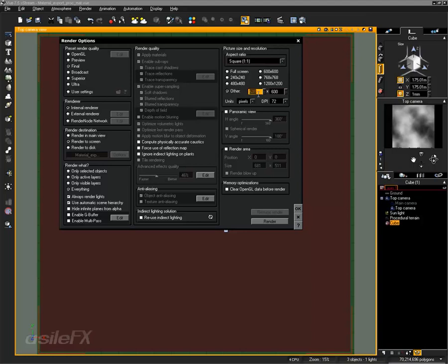So using a very high resolution is suggested, and no problem at all. So you could set this all the way up to 6,000 by 6,000 without a problem. Once you hit the higher resolutions, basically anything beyond 3,000, 4,000, you want to make sure you're using the render to disk rather than render to screen.